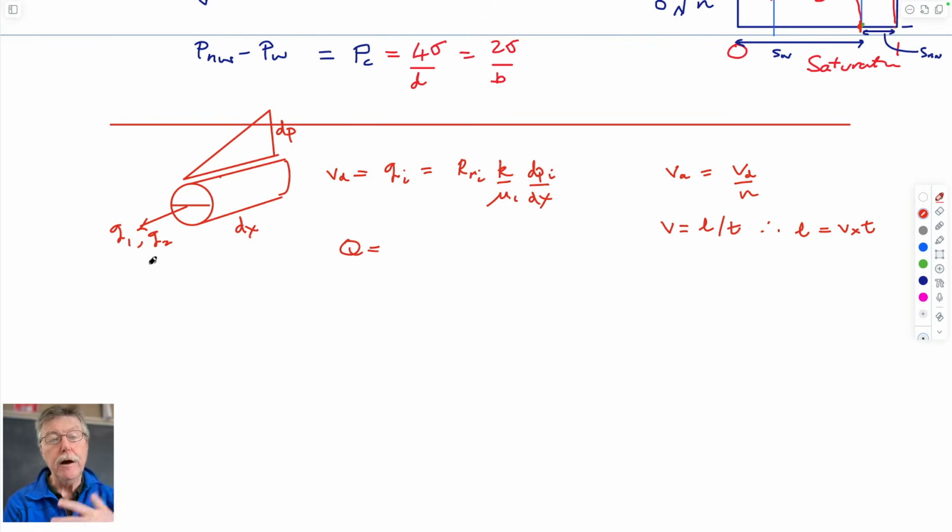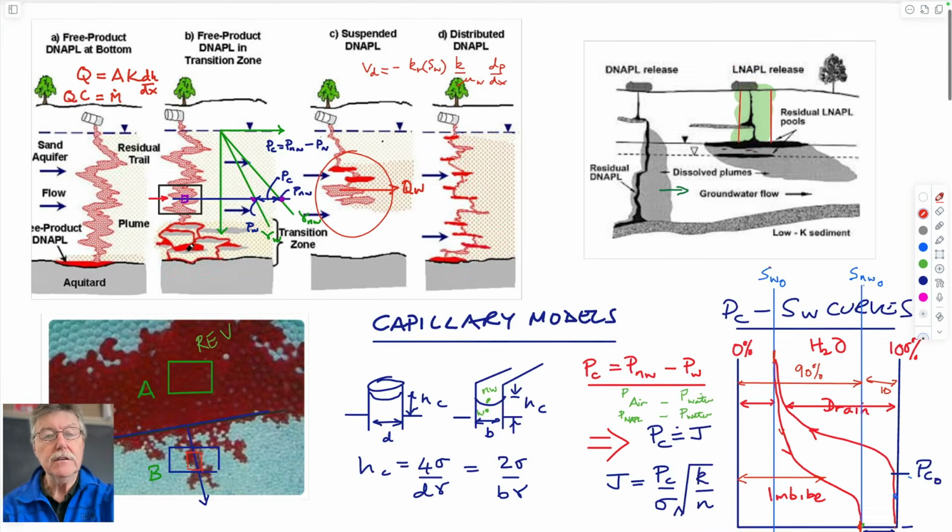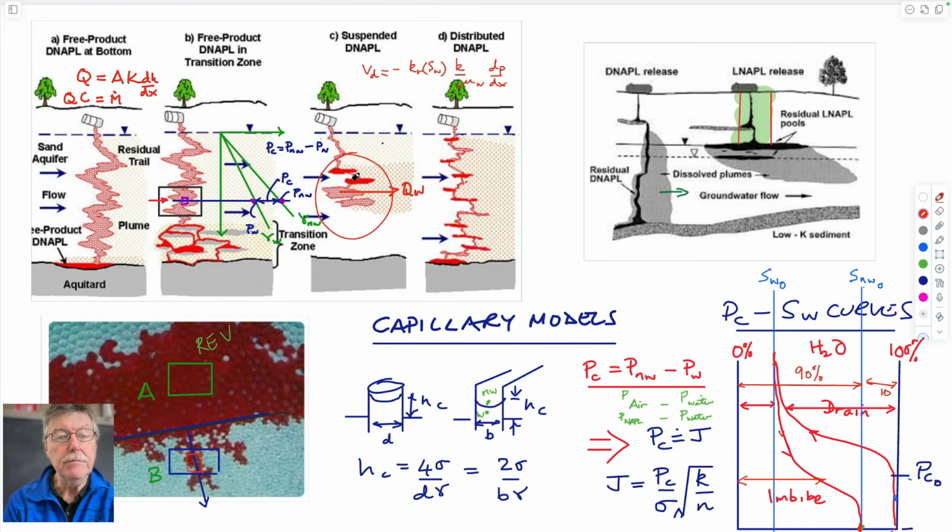Sometimes one fluid is immobile, such as NAPL caught by meniscus forces when it's at low saturations. If they're both in roughly equal saturations, we know that both can flow. But what we're talking about for contaminant transport is having water as the transiting fluid, with NAPL present at relatively low saturations, having lots of contact area with the water flowing past it, and therefore being able to pick up dissolved components.